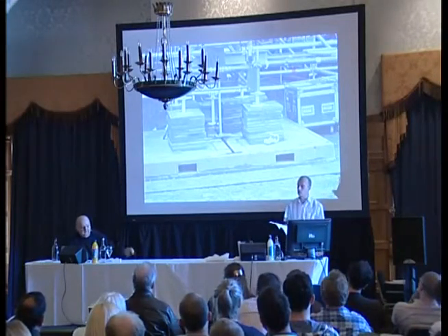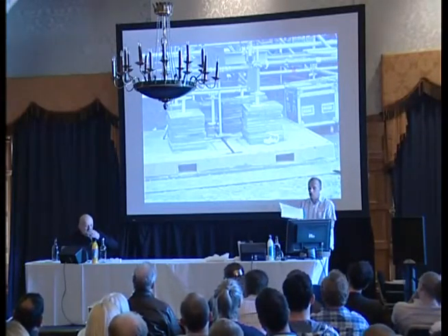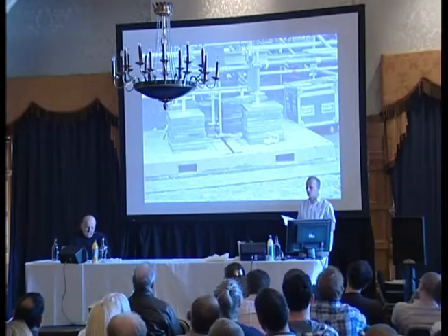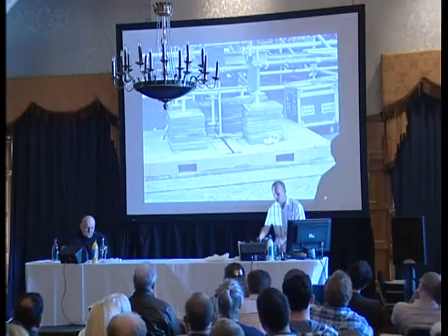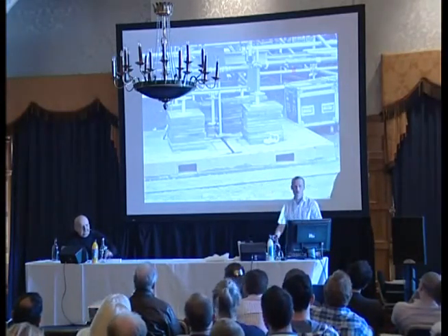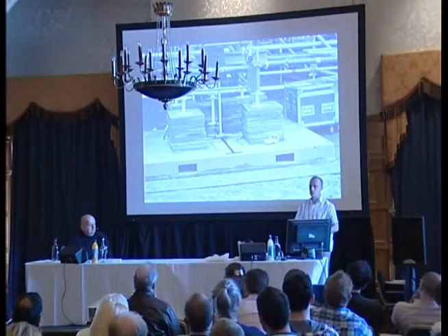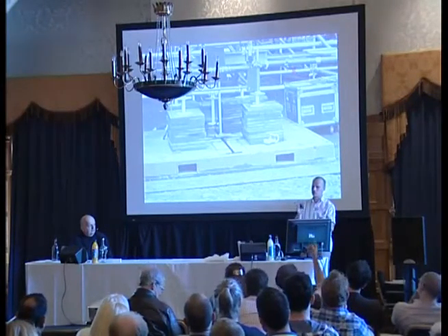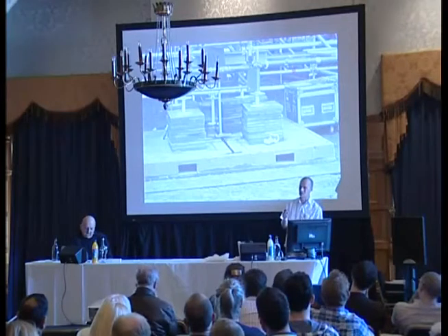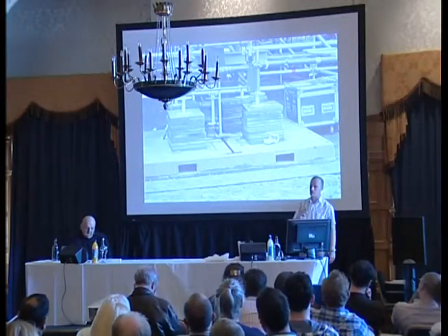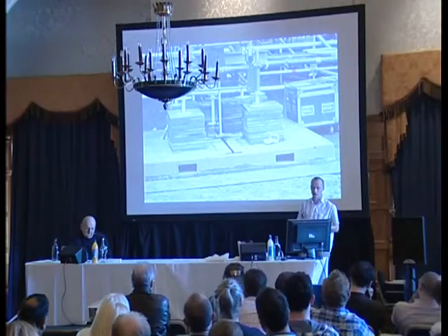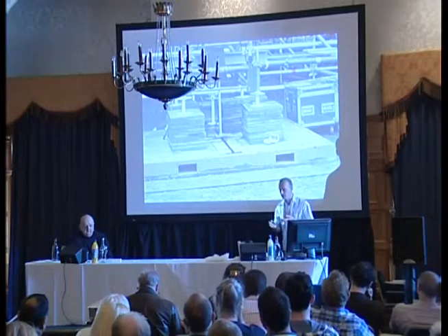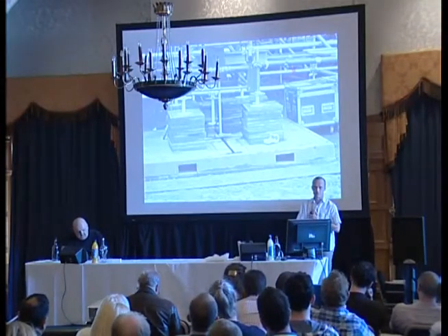Have you done a stake pull test? And I know, one of the things that Tim's talking about, at all your sites now, you carry out a stake pulling test. It doesn't have to be thousands of pounds worth of testing. It's a dynamometer and a forklift, or a JCB. You bang a pole in and you see how much it takes to pull it out. That doesn't take thousands of pounds, but it gives you an idea of your ground. It's not your ground bearing pressure, that's certainly your stake pulling, so it's the opposite, but it helps. You need to know. And again, it doesn't mean you have to go and get a soil survey company and spend thousands of pounds to have it done.